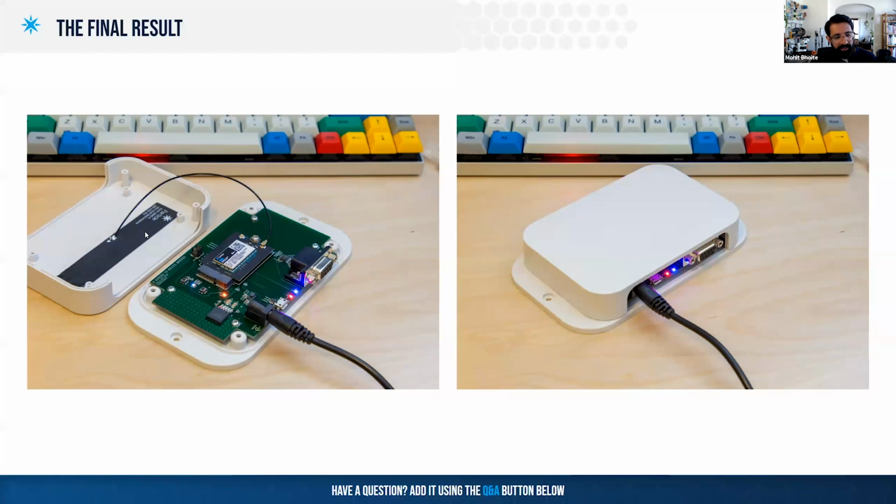The antenna, as you can see on the left here, is mounted on the top of the enclosure. While it may seem that you put an antenna on and it should work, you may run into issues with antenna performance because there is so much metal around the antenna. The radiation pattern and its resonant frequencies might change. So you will need to pay attention to that and work with your antenna vendor or your RF lab to help you tune those parameters. But again, we'll talk about those things in a future webinar.